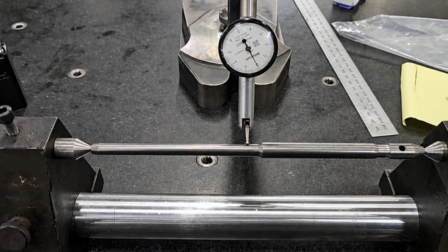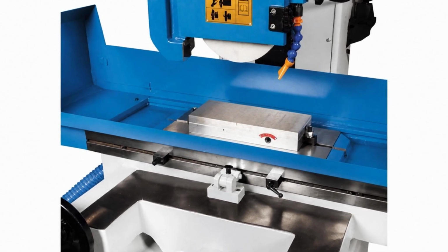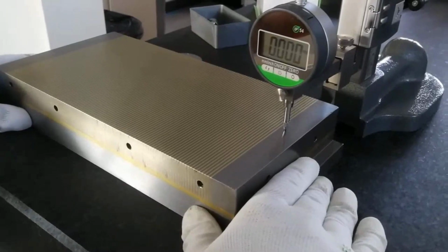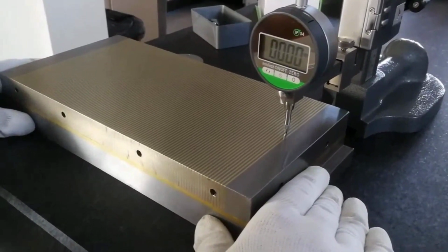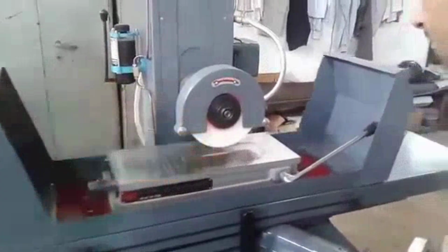To achieve absolute squareness, the machinist transfers the blanks to a high-precision surface grinder. In this measured, tactile process, a grinding wheel gradually lowers by tiny increments, often just 2 microns per pass, gently sweeping across each face. This gradual shaving removes the highest points, squaring the block until all 6 faces meet at precise 90-degree angles.